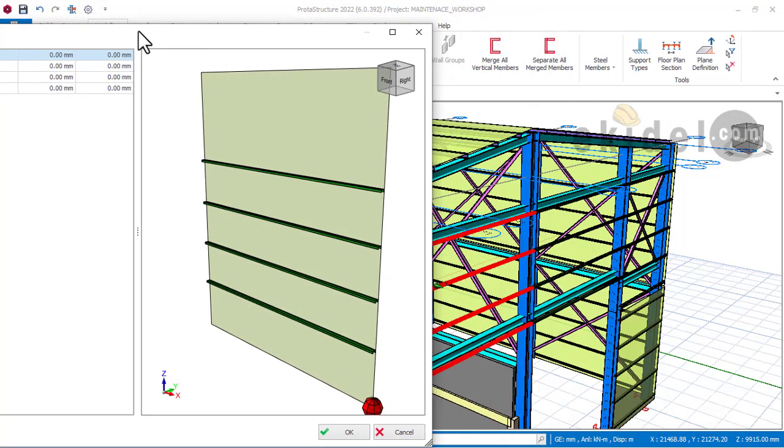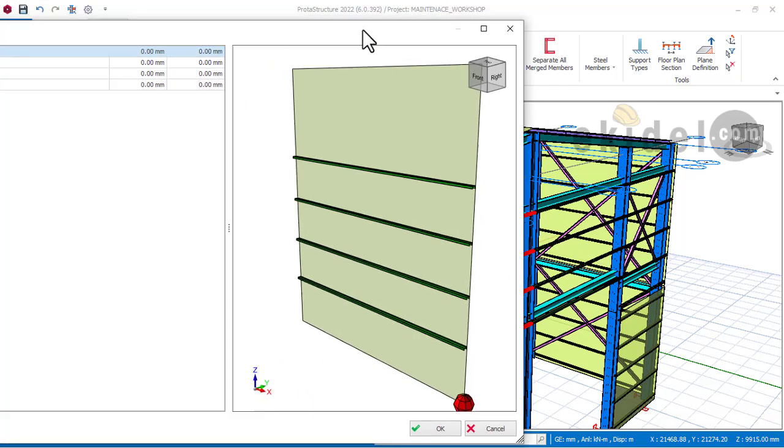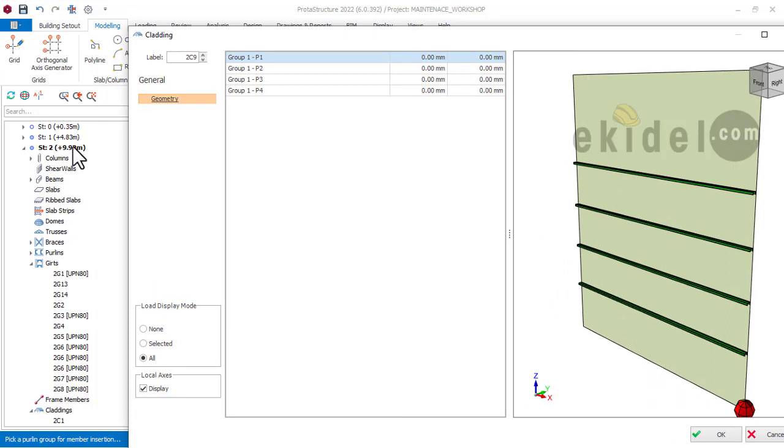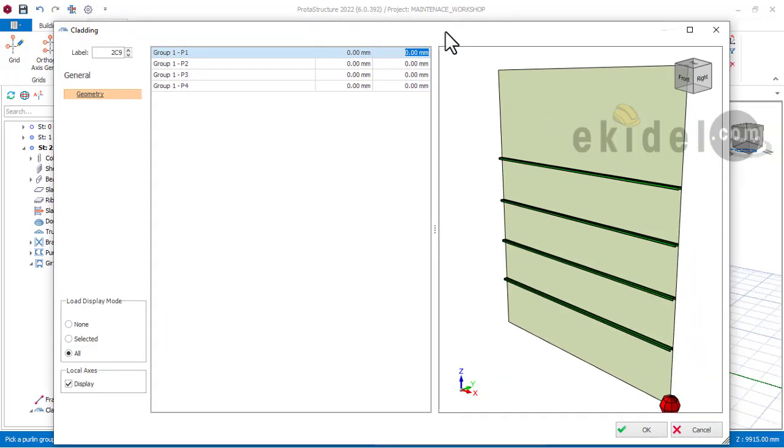Now, based on this structure here, I have already been given my heights, and you can see that I have different heights here. I have already calculated my elevations, and these are the values that I'm going to put in to fit that very shape. So if I go here and put in on this place, which is the P1, I'll put in 1115, which will take care of that excessive cladding that was going through that entrance area.